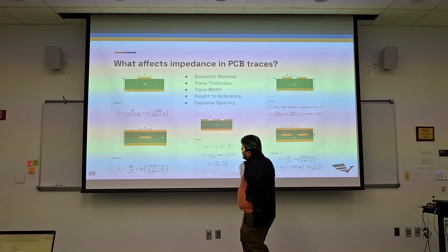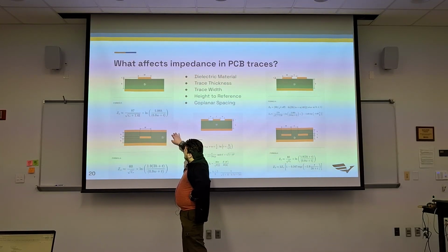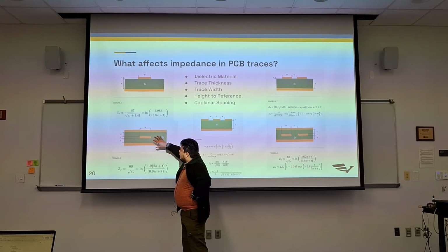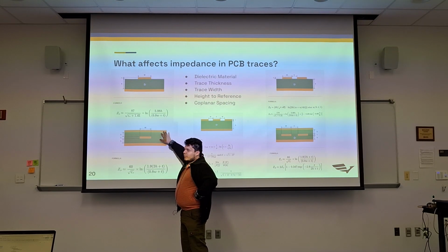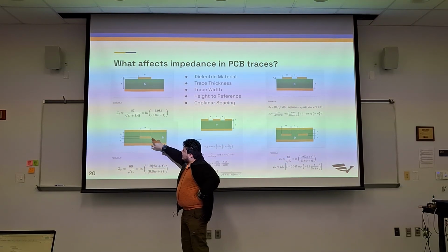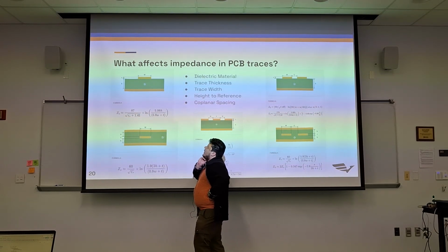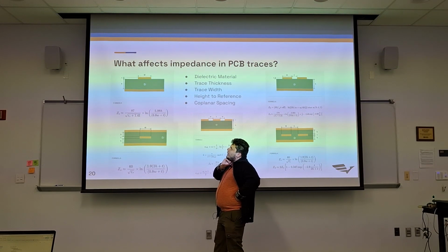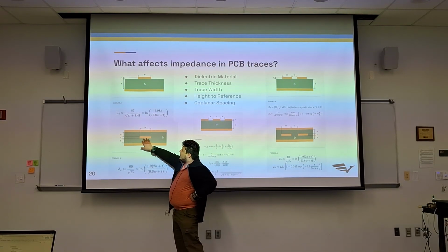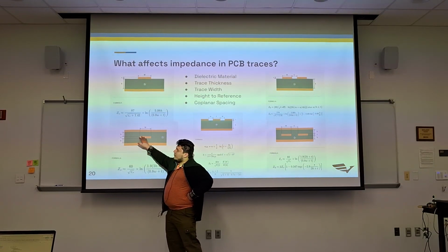Okay. Yeah, so basically if this was a 4-layer board, for a reference you want it to be a solid ground plane. So this is probably not going to be your top layer because that's where your component paths are. So you can imagine this being layer 2, layer 3, and then layer 4. This is assuming that you are able to route all of your power on layer 1, or that you are able to route this such that your power planes are not on top of this.